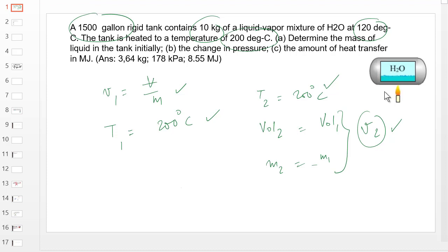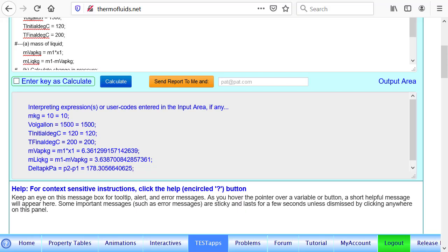Well, we don't know how to calculate heat transfer. That is covered in a different class. But if we can somehow know how much the energy in the tank increased, that must be because of heat. Suppose there was 100 amount of energy in the tank, and I put in 20 amount of heat. Then the final energy will be 120. Put another way, if I know the final stored energy and initial stored energy, the difference must be the heat supplied, the energy supplied. And heat being the only way energy is being transferred, we are ready to do an energy analysis.